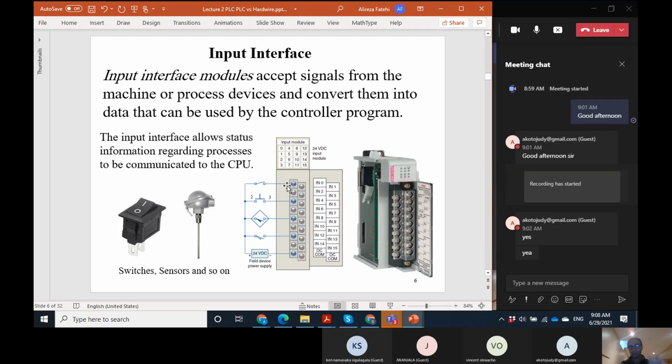Of course, you have current base, but these are voltage base. But so the voltage change, or let's say electric signal change, the PLC card measures that electric signal, that voltage, and then let's say assigns the value of some memory in the PLC.